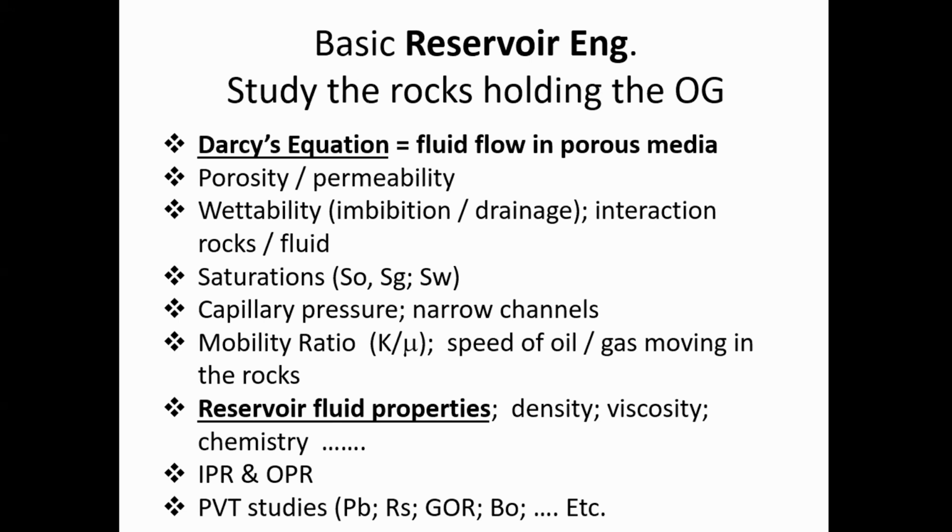You need to understand something on IPR, inflow performance relationship, or OPR, outflow performance relationship. You need to understand something on PVT of the crude oil, such as formation volume factor, solubility, bubble point pressure, and many other factors.